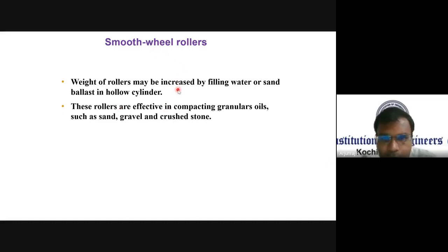And smooth wheel rollers' weight may be increased by filling the hollow cylinder with water or sand ballast. These rollers are effective in compacting granular soils such as sand and gravel, and they can also be used for handling crushed stone.